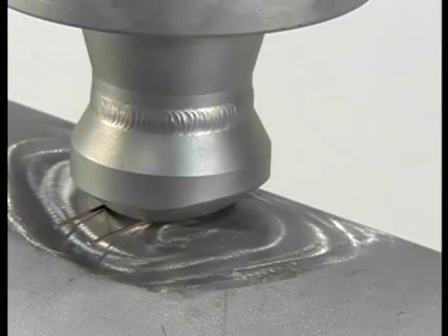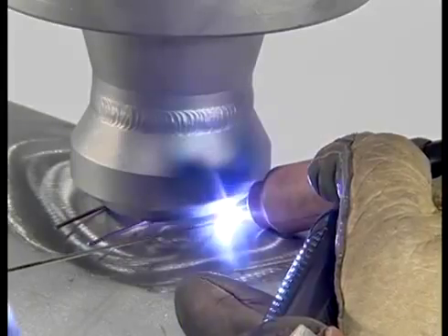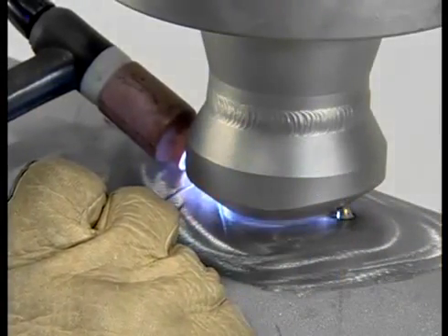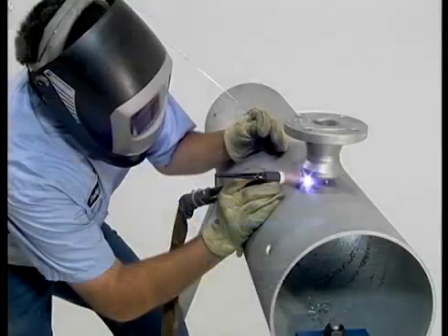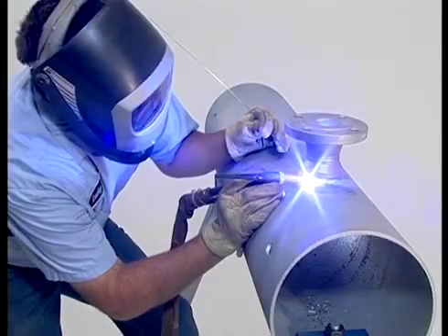With the mounting hardware aligned correctly, you are now ready to tack weld it in place. Make your first tack weld anywhere on the hardware, then again directly across from the first weld, and finally on the other 2 sides at 90 degrees.